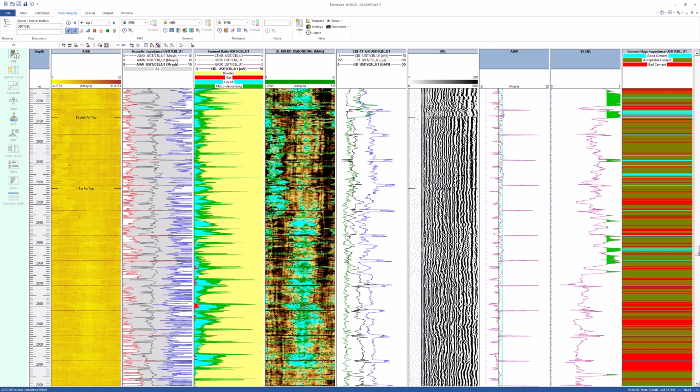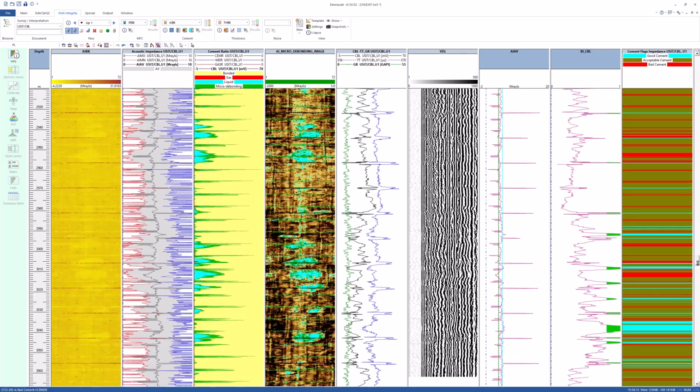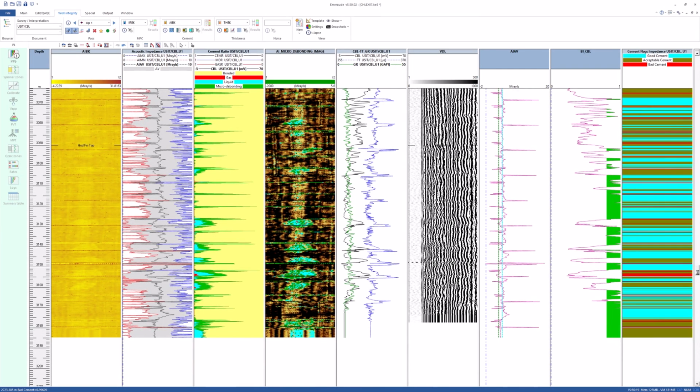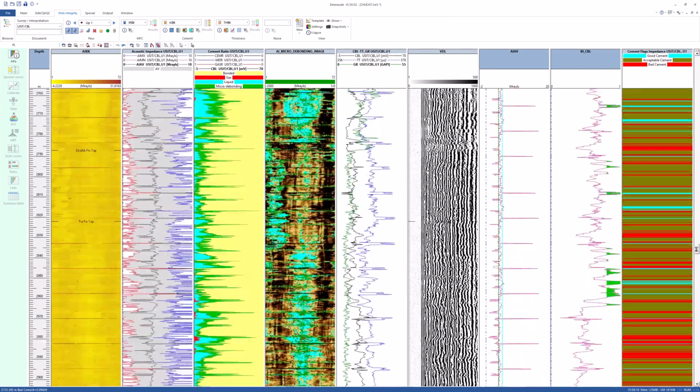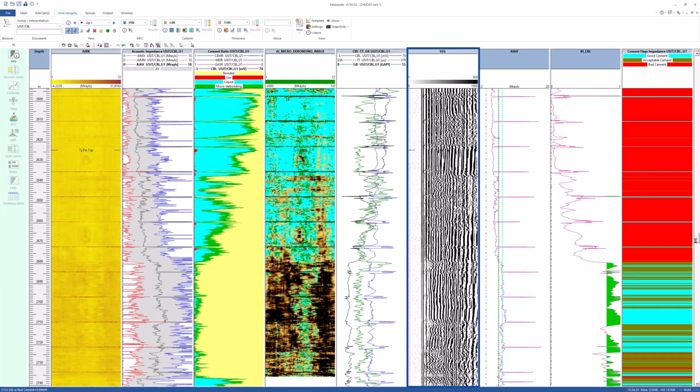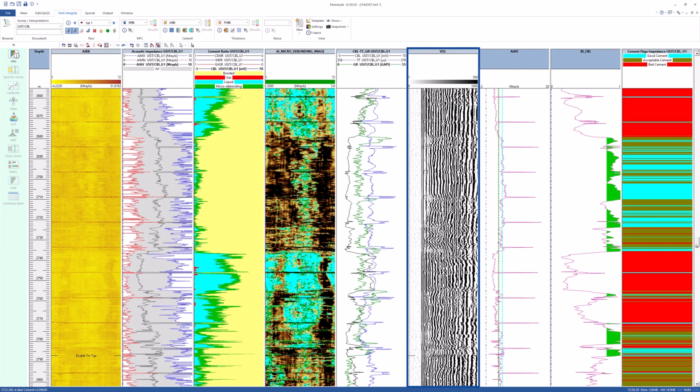The next step of the overall isolation criteria is the cement-to-formation analysis. When the sonic wave propagates into the formation, changes in lithology are reflected in the VDL as crooked lines after the early casing arrivals. Click on New User View.